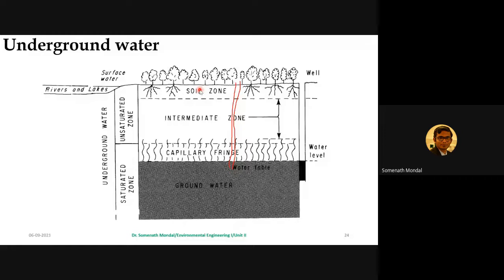Fine. So if you see, water in the capillary fringe and in the overlying part of the unsaturated zone is under a negative hydraulic pressure. Fine. And that is, it is under a pressure less than the atmospheric pressure or the barometric pressure, because of the suction, water is getting up now, and going opposite to the gravity. Now the water table is the level in the saturated zone at which the hydraulic pressure is equal to the atmospheric pressure, and this is very important to remember, right?